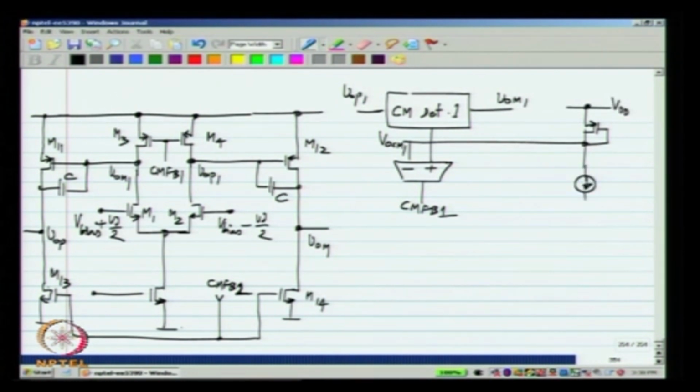And what is the meaning of the correct quiescent voltage? It is the quiescent voltage that establishes the desired current in the second stage. We need a certain quiescent current I12 in the second stage. So, that can be done by having a scaled replica of the output stage in the biasing branch. This replica biasing is a very common thing that is used in analog circuits.